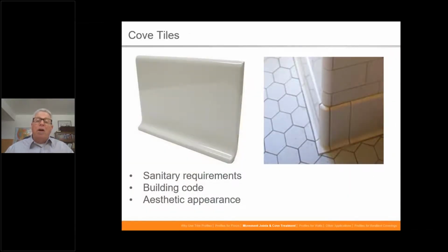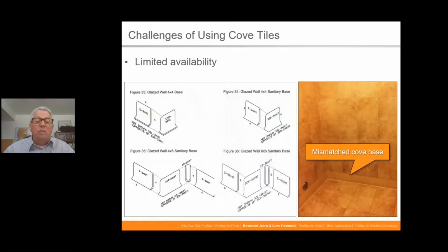How about Cove? Back in the day, there was a lot of tile that was available with a Cove base. Now, why would you need a Cove base? Well, moppable, keep it clean, easy. In a lot of food service area, it's a requirement, and it can be an aesthetic thing, so keep that in mind. But again, there aren't a lot of tiles that are available with Cove any longer, not like it used to be. And you can see the type of different pieces you needed to execute a job, to turn an inside or outside corner and cap it off correctly, whether it was a moppable Cove or a top set Cove.